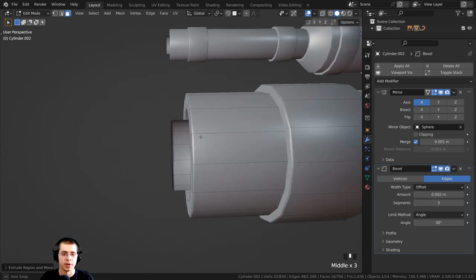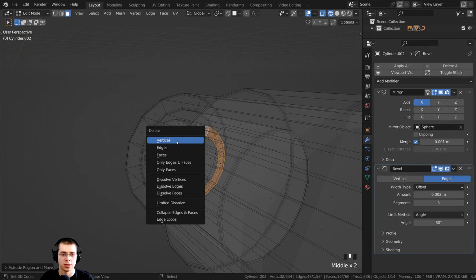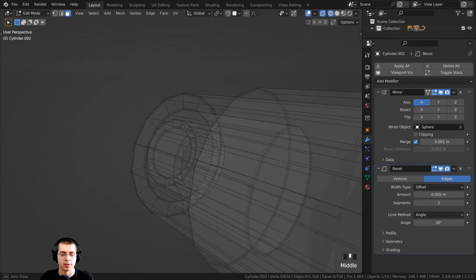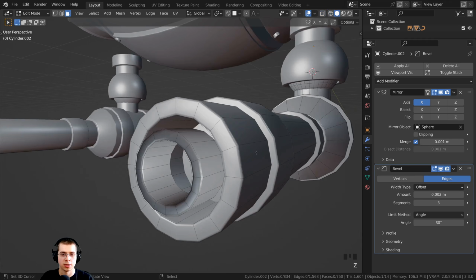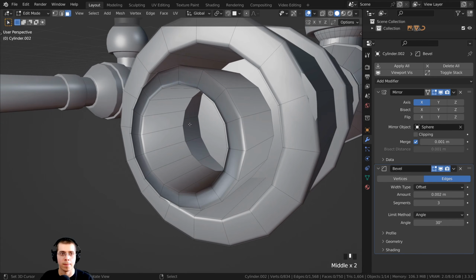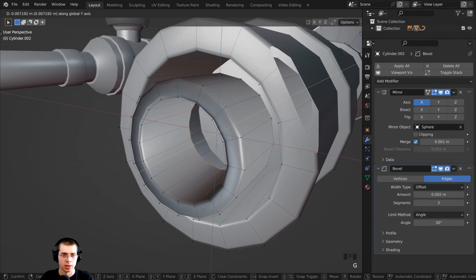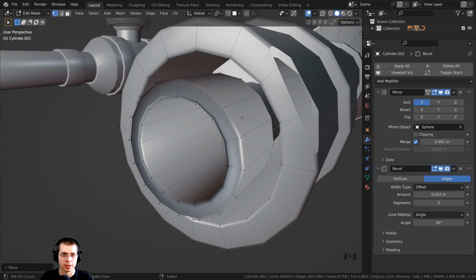And then we have some extra faces in there that we don't need. We don't actually need those faces. So I can press X to delete, and then we can delete the faces. All right, I'm gonna hold down the Z button to go back into solid view. And then you can see that that piece right there needs to go farther back. So I'm gonna go right here to the Vertex Select, hold down the Alt key and select that loop of vertices. I'll press G to grab, click with your mouse wheel, bring it back on the y-axis,